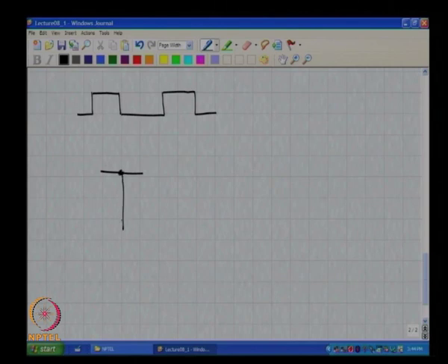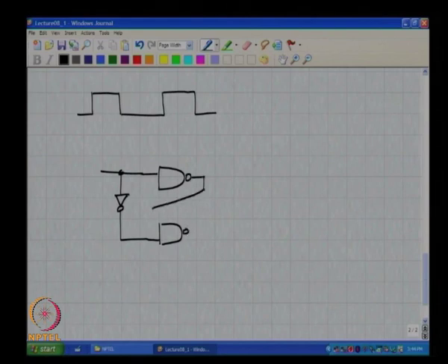At this point I will not do that, I will just quickly show you the core of the circuit and analyze it and show you that it works. And those of you interested can actually go and see how we can come up with the circuit from first principles. So, the core of the circuit is an RS latch made with NAND gates, for argument's sake, let us assume that the inverter is delay free, but the two NAND gates have delays Td which are deliberately made large, okay. Why do you think we would want to make them deliberately large?